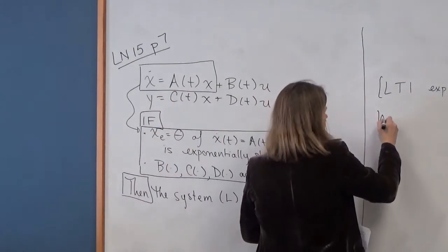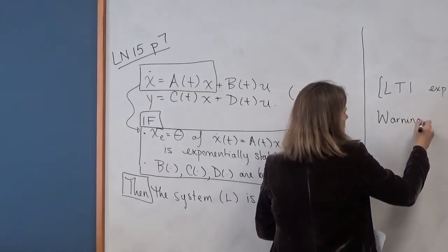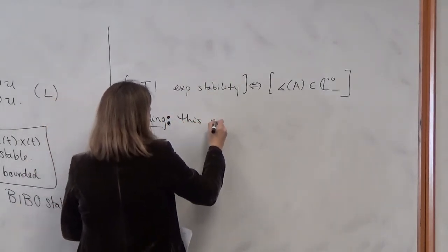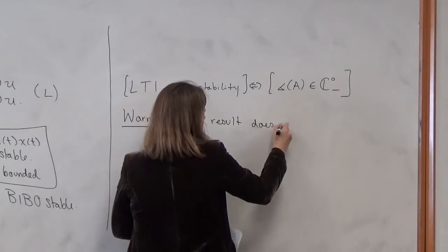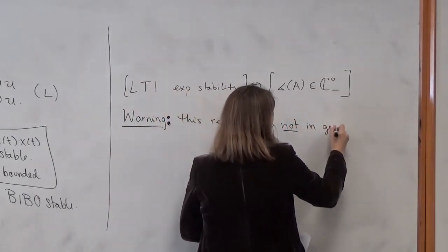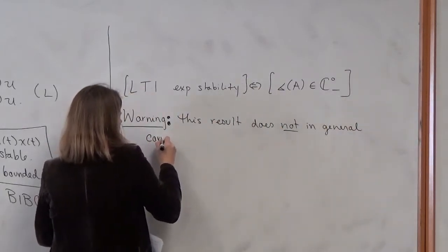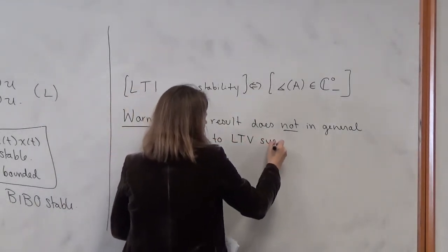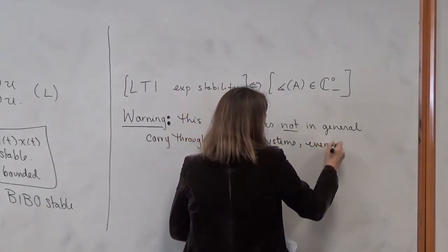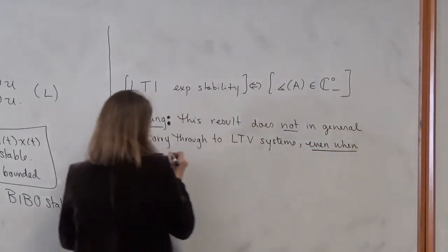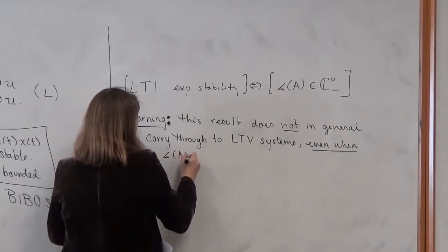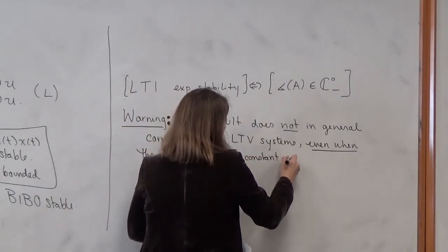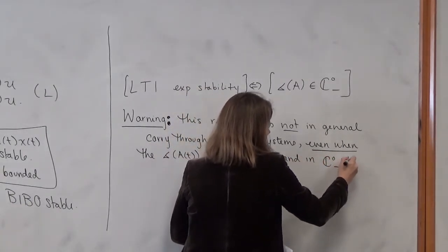Warning. This result does not, in general, carry through to time-varying systems, even when the eigenvalues of A of t are all constant and in the open left half plane.